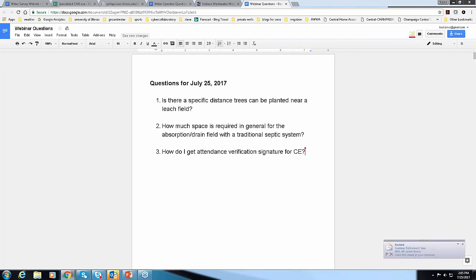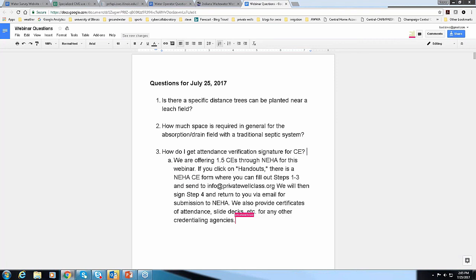From that soil comparison you determine how big a leach field you need, and it's also based on flow, which is based on the number of bedrooms. There's no easy answer, and each municipality, state or county will have different regulations, but the easy answer is it varies based on a number of conditions.